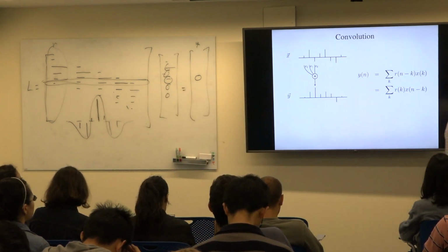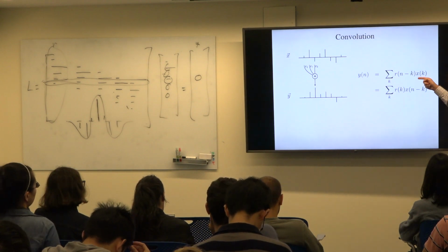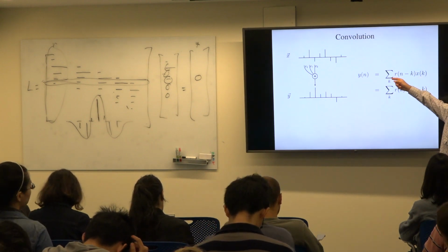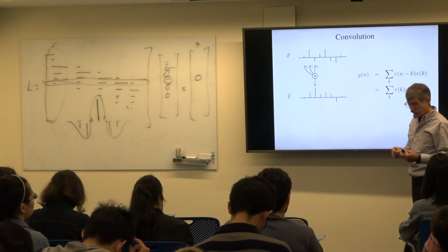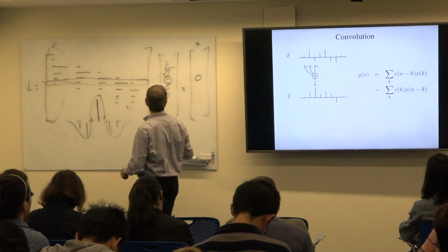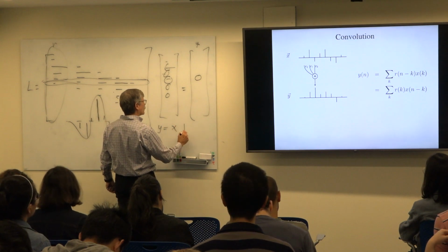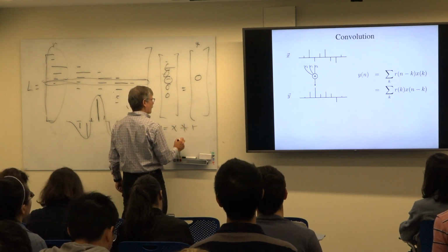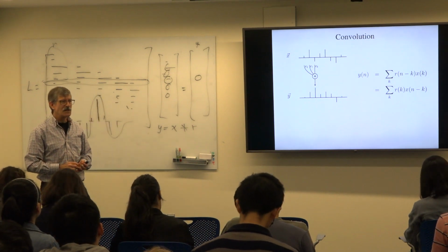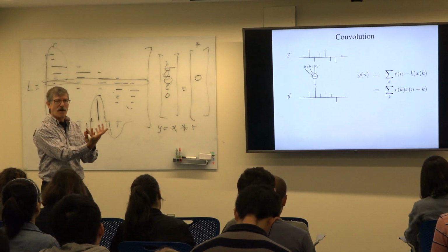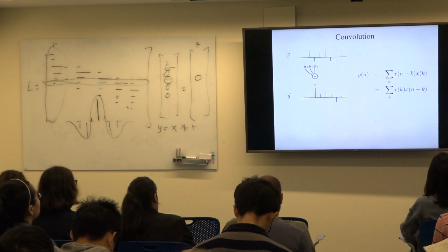And so the idea of convolution: what we're doing is an operation that combines the input x and the impulse response r. And this formula is called convolve x with r. I don't know if the notation's in the next slide, but we can say that y is x, usually a star, r, where star stands for not multiply, but convolve. It's something that takes two functions, takes one of them, flips it with the other, and then dot products it at various locations.